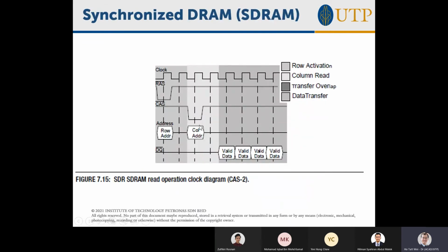So what I'm saying is, again, this idea of pipelining. The idea of pipelining is that you have an operation that is taking a long time and is using different parts of the circuit. So I can actually do in parallel, but not exactly at the same time. I just start one task first. Then as that task goes on to part B, I can start the second task, part A. As task 1 goes to part C, task 2 can go to part B, and I can start task 3 in part A, right?